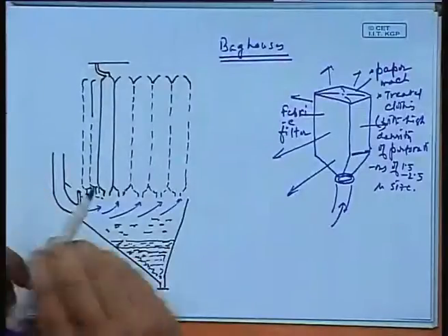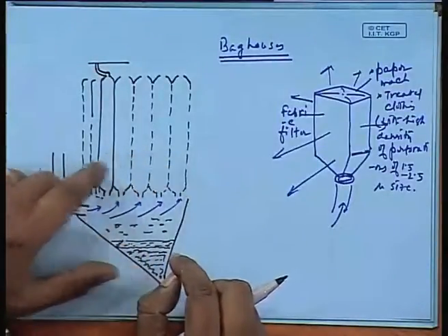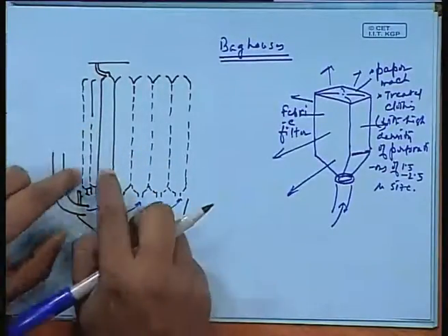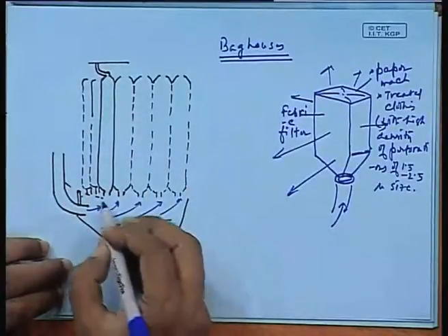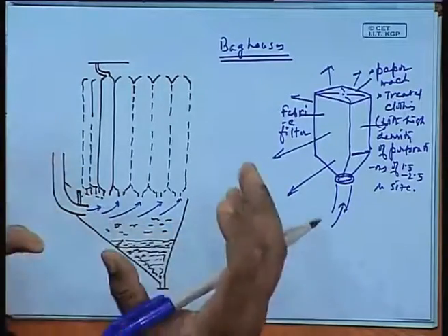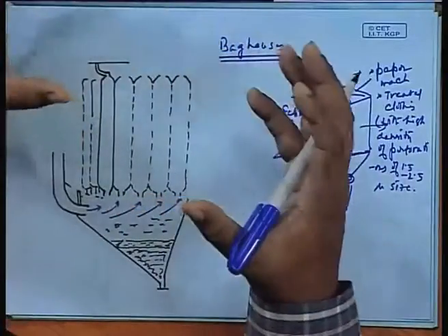This is a typical bag house, with columns of bag houses like this, 1, 2, 3, 4, 5, and then on the other side, so you can see 6, 12, 18 bag houses. The air enters through a common entry and is directed to each of the bag houses, and goes out through these bags, and the particulates settle. Some remain stuck in the bag, and many settle down.